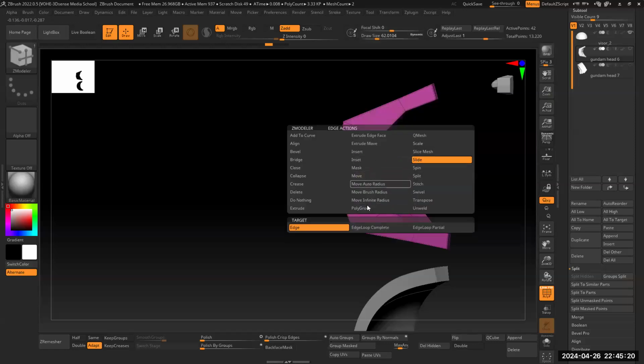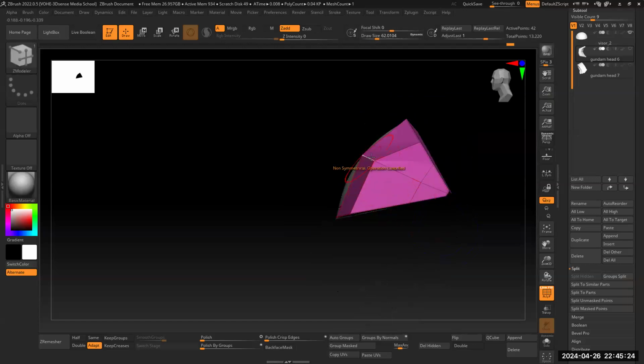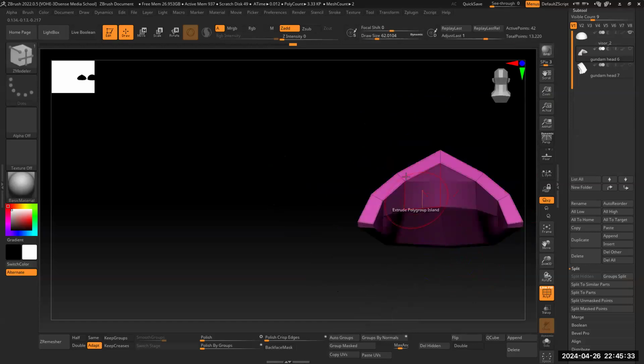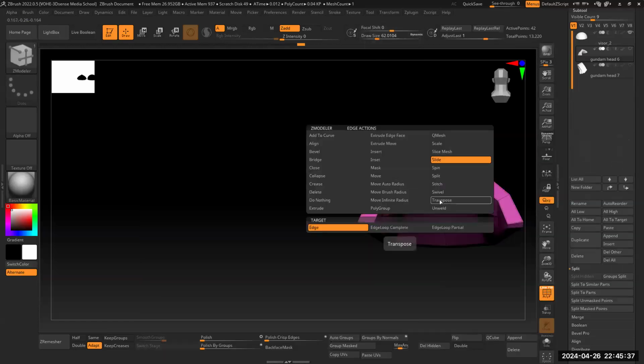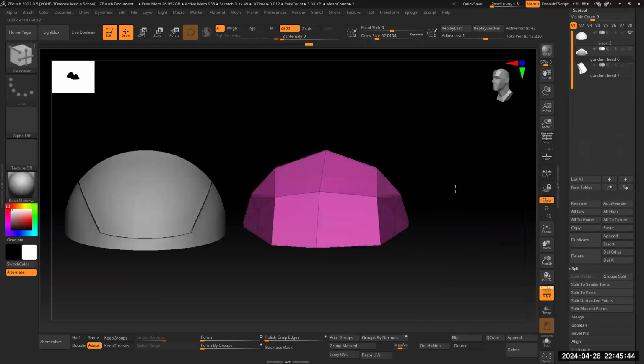Another good one is slide your edges, right? So I can really just use the slide to shift stuff around, right? I can do this sort of adjustment in ZBrush, right? In Maya you can do it too, but I find it faster, right? Okay, let me fast forward again, move this edge, right? So I can make very fast hard surface or very basic adjustments using ZModeler, right? Right now our thing is off symmetry already.